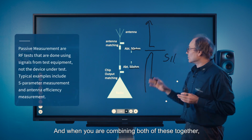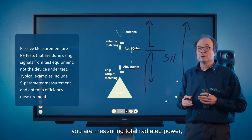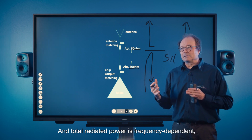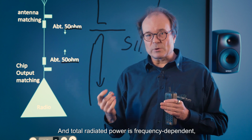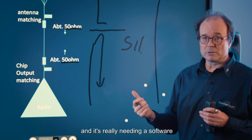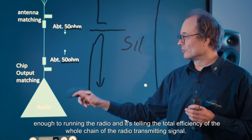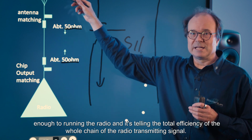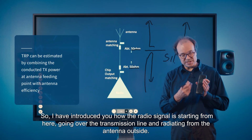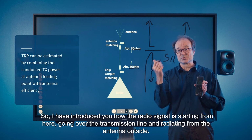When you combine both of these together, you are measuring total radiated power, so how easily the radio signal comes out. Total radiated power is frequency dependent, and it needs software that is able to run the radio. It tells the total efficiency of the whole chain of the radio transmitting signal. So I have introduced how the radio signal starts from here, goes over the transmission line and radiates from the antenna outside.